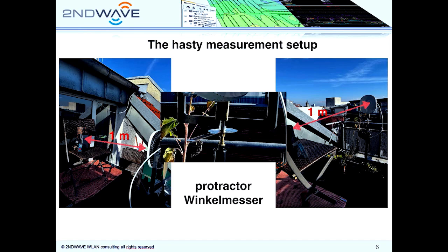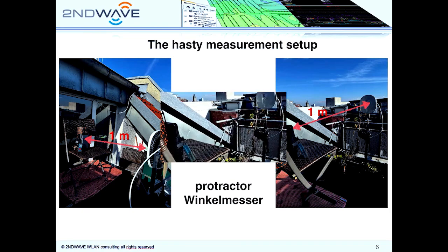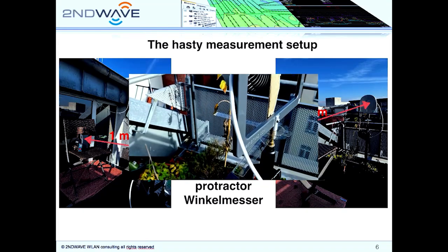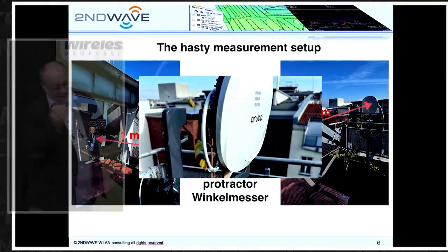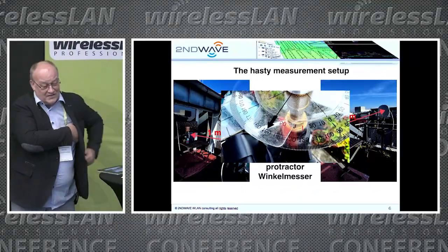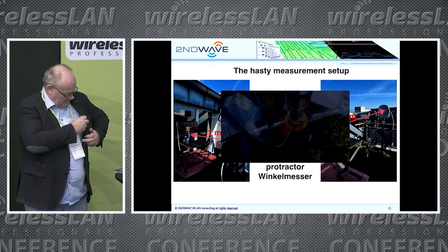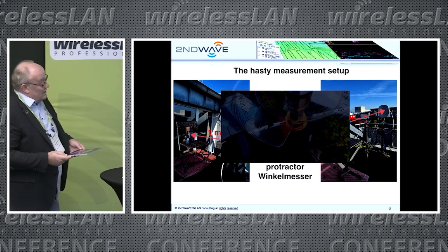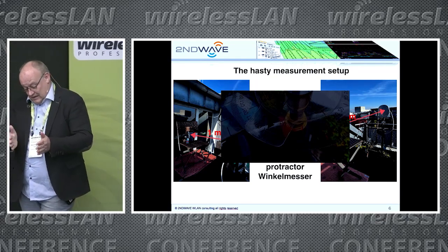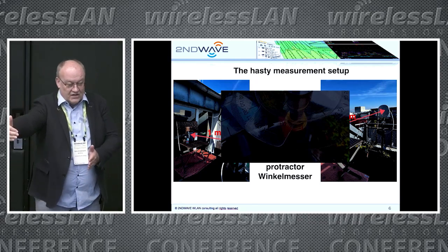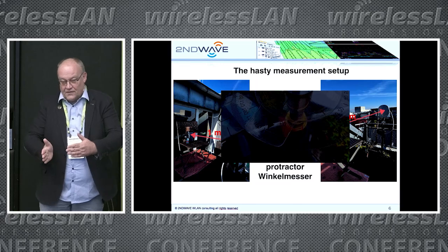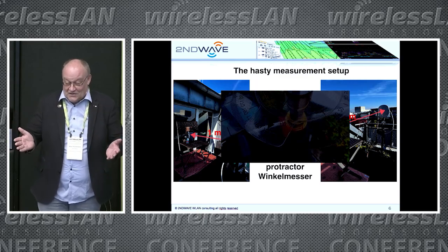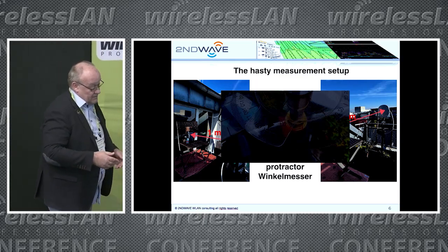What I used to measure the angle, you may see it, and I have it with me, this one. One I had to destroy because of the tripod. Of course, the original device I also have here, so if one wants to see, very easy. So the measurement was, I'm taking the angle, measuring the RSSI, changing it by 30 degrees, not 5 degrees or 10 or 15, because it costs a lot of time to put together all the measurement points.